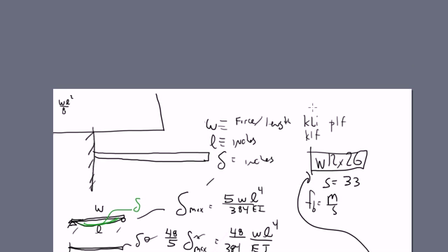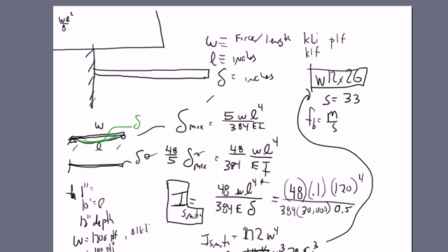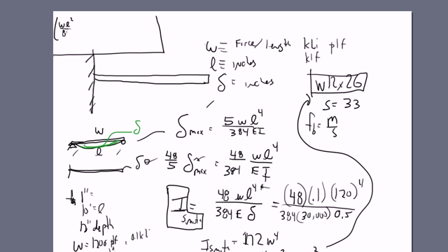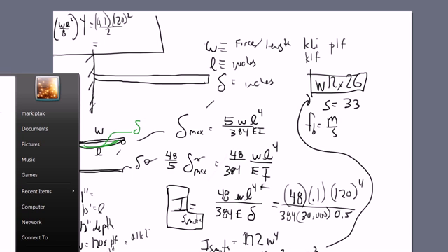See, that one got a little screwy on me as I grab that, jumping around. All right, WL squared, you take that, multiply it by 4, knowing it's 4 times worse on a cantilever than it is in a simply supported uniformly loaded beam. And so now you have, once again, your little W being 0.1 as the case may be. Length is 120. This time it's squared over essentially 2, and that's going to be kip inches, and so we've got 120 squared. Back to the calculator.